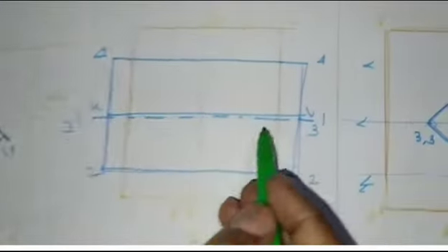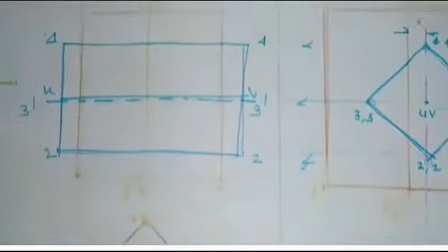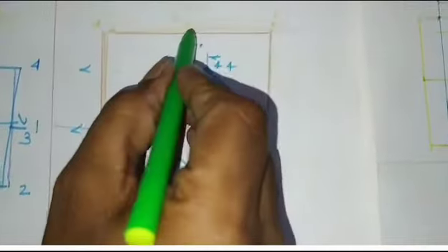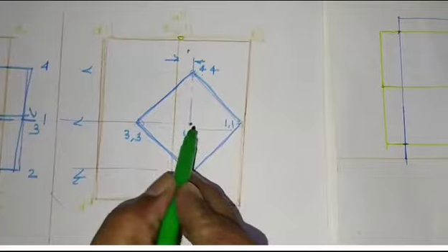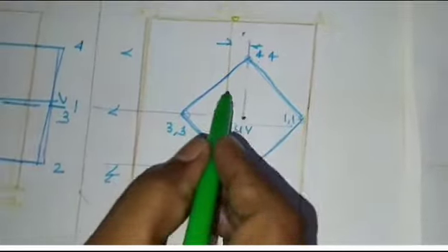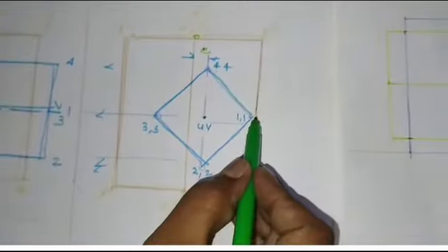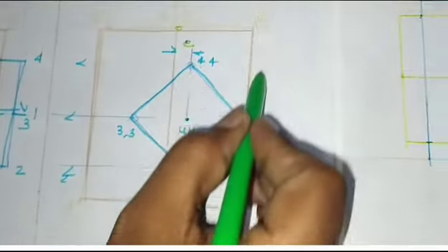Now in the second figure, the same object, same solids, vertical solid and horizontal solid, square prisms. Now this axis is shifted. This is OP, and this axis UV is shifted in front of this axis, to the front side by some eccentricity. But this corner of the horizontal solid is not crossing the vertical solid.